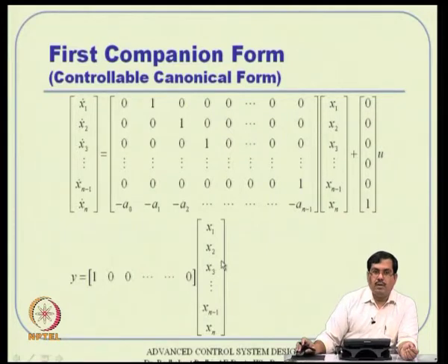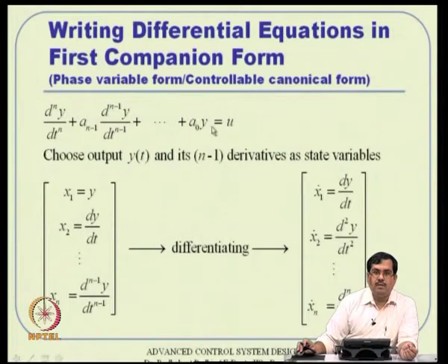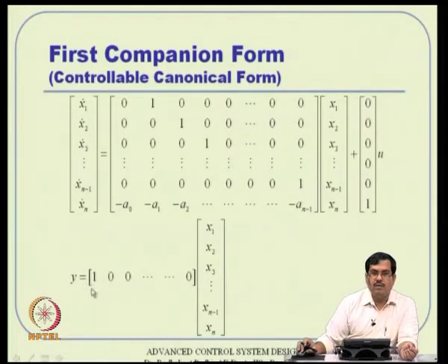Okay. And then if you talk about output, and let us say primarily my displacement is my concern, that y, then y is nothing but x1 only. So, I will write y is equal to x1, but I have to represent it in the form Cx plus Du. Then C matrix is 1 0 0 0, a row vector here, followed by the same state vector, plus Du, and D is 0 obviously here. So, you got A matrix, you got B matrix, you got C matrix that way.